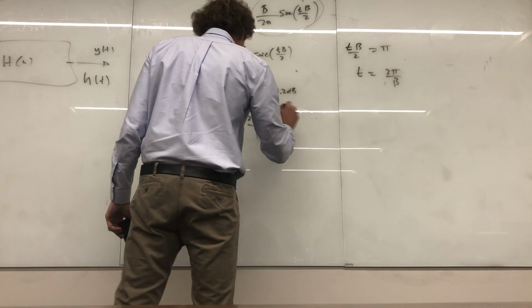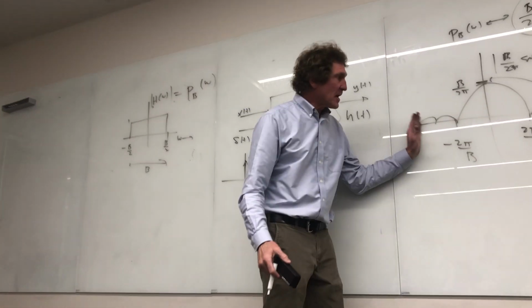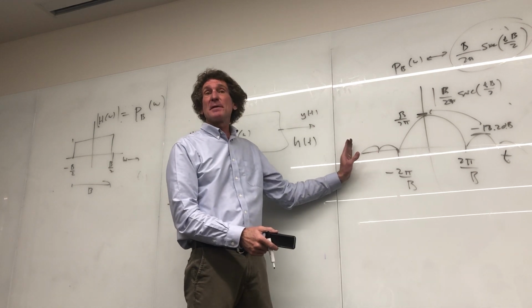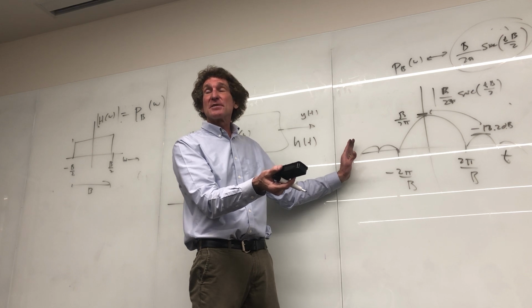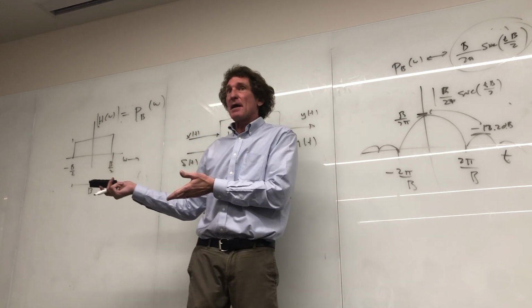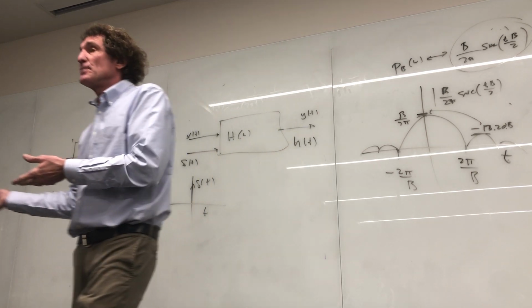Now, when I look at this function, this is the eerie thing. This is in the time domain, right? What caused this function? A delta function like this in the time domain, correct? Now, I want you to think about this logically. This is negative time, right? Before the event happened that created it, it's already spitting out output. It's anticipating that function. Do you follow me on this? That's impossible. That's a non-causal response to an impulse response. Y'all see? That's negative time. Take negative 5 seconds. There's something there, but the input didn't happen. How does it know it's going to happen? It doesn't. That's an impossibility. That filter you can't build.